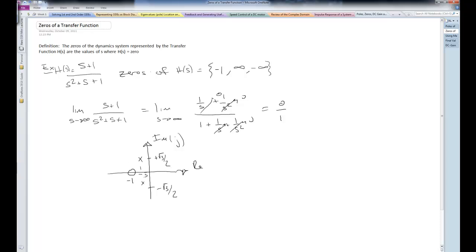The finite zeros are known as the transmission zeros, because when we're at that zero, the signal is not transmitted. So it's a way of where the plant blocks the input when I'm at a zero, because the transfer function takes on the value of 0. You can think of it that way.